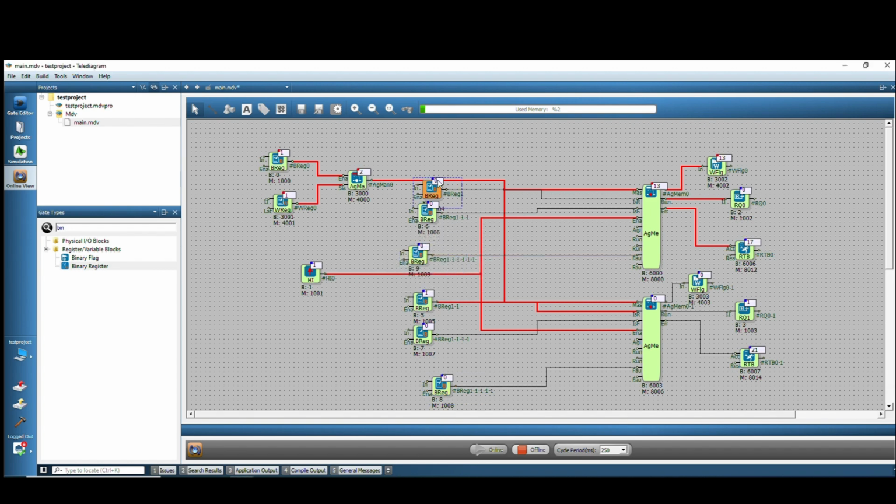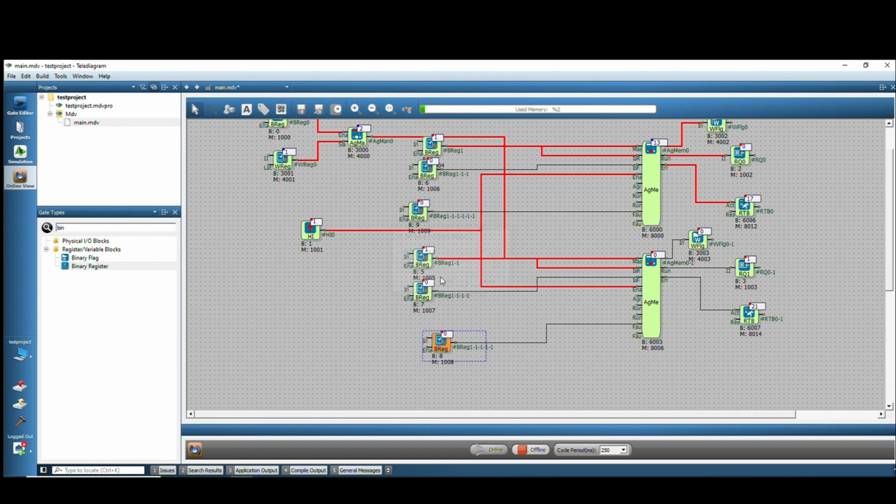Let's bring it back to 0 again. Again, if the working information does not come for 40 seconds, it will return to 0 again. But since we want it to work properly, we sent 1 to the working input of roll 0. As seen in the word flag block, it shows that it has been working for a minute on the block. These blocks have a persistence feature. Even if it receives a reset, you can observe how many minutes it has been working.